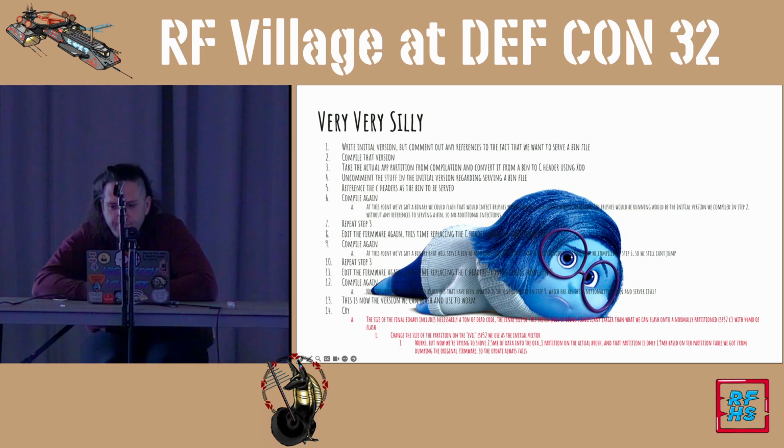And that'll work, except that then essentially you end up trying to shove 2.5 megabytes worth of data into the OTA partition on the actual brush, and that partition is only 1.9 megabytes based on the partition table we got from dumping the original firmware. And so unfortunately the update always fails because we're trying to put 2.5 megabytes worth of data into a 1.9 megabyte bag.